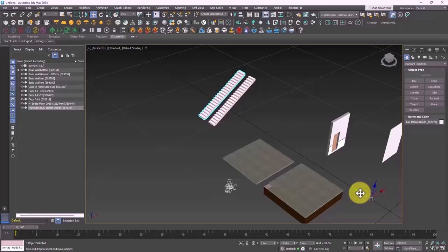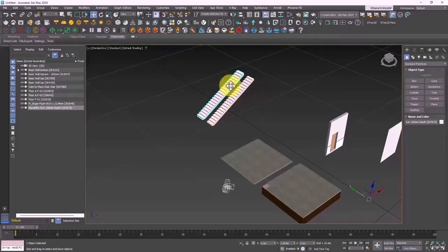But we have this problem for curtain walls as well, or even the patterns of the mass. If you're using mass, when you use them, your file suddenly will be really heavy, and it can cause this problem for curtain panels and also stairs and the patterns of the mass, unfortunately. And we can do nothing for it. The only thing we can do is deleting them.